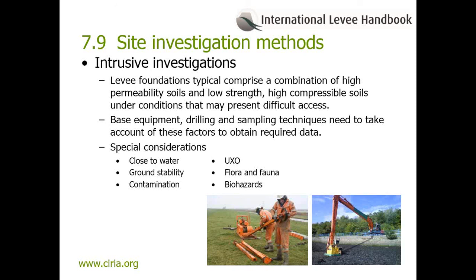Illustrated below are just two examples of special equipment designed to operate in areas of difficult access. These are the modular cable percussive rig, and a CPT on a long reach excavator. Other specialist equipment is discussed for operating on slopes, over very soft ground, or where there is a restricted width access.